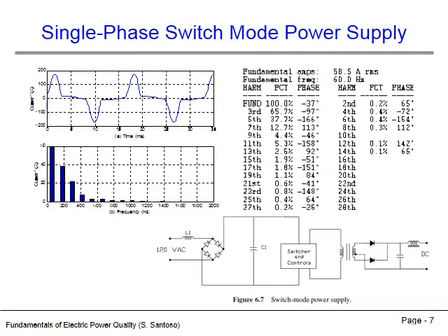The figure in the top right shows another example of the current drawn by a nonlinear load, a switch-mode power supply. To the right, measurements of the phase angles and magnitudes relative to the fundamental of each harmonic are shown. Unlike the previous example, all odd-numbered harmonics are present in this current waveform, and the component's magnitude tends to decrease as its harmonic order increases. Even-ordered harmonics are essentially absent in this current waveform, as is usually the case in power systems.